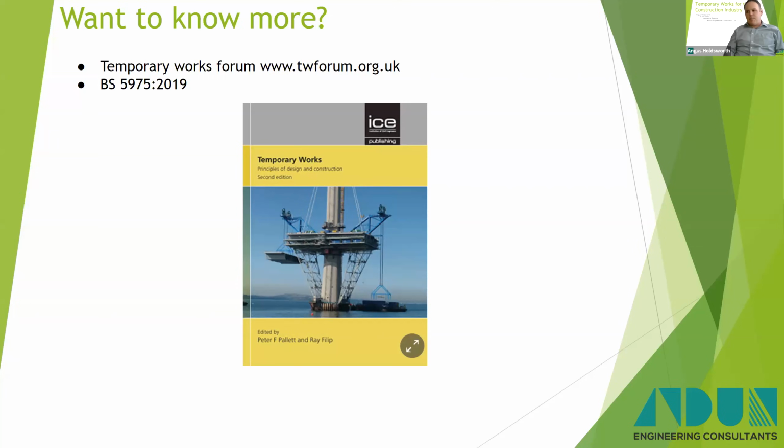Cat 3 checks are supposed to be for something that's novel and unusual. I would say they're overused by clients; Network Rail in particular often insist on Cat 3 checks where I don't necessarily think they are required. The only difference between a Cat 2 and a Cat 3 is that one is done by an external company. A Cat 2 could be undertaken and give you the same output.